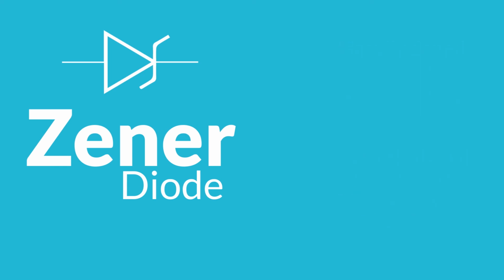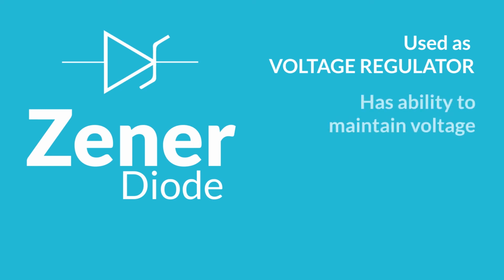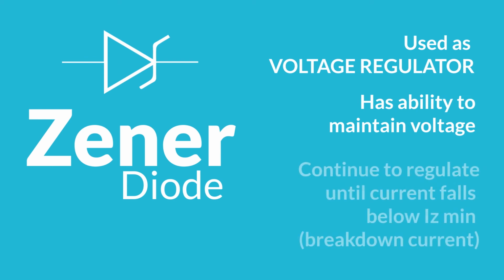A Zener diode is usually used as a voltage regulator due to its ability to maintain voltage under reverse bias condition with large current changes between the breakdown current IZ min and its maximum current rating IZ max. A Zener diode will continue to regulate its voltage until the current falls below the minimum IZ min under reverse bias.